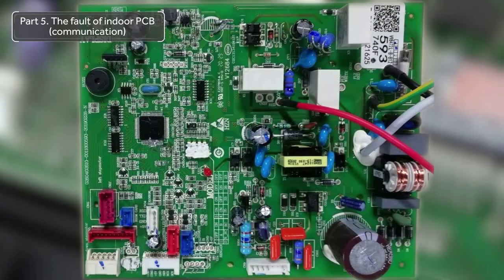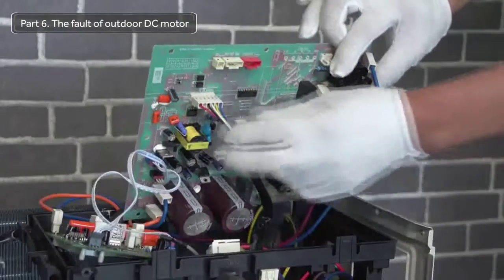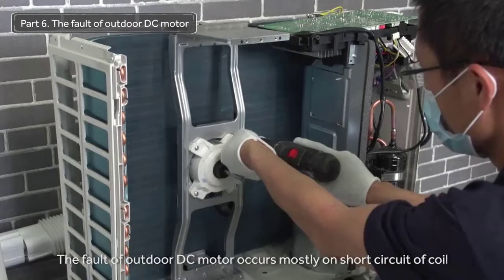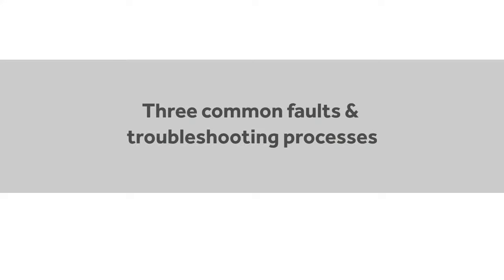Part 5. The fault of indoor PCB. The communication fault of indoor PCB is rare because the indoor temperature and humidity are relatively constant. Part 6. The fault of outdoor DC motor. The fault of outdoor DC motor occurs mostly on short circuit of coil that causes no 5-volt voltage input to the outdoor PCB. 3 common faults and troubleshooting processes.